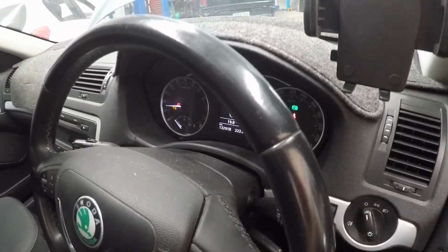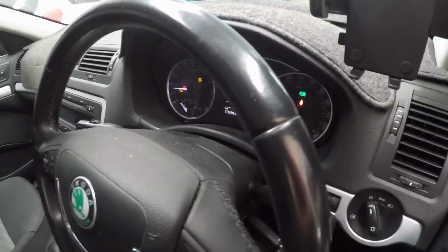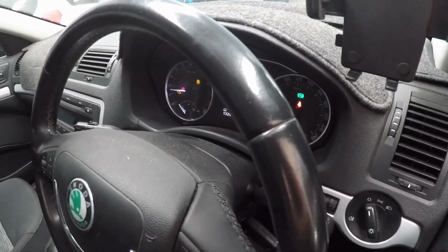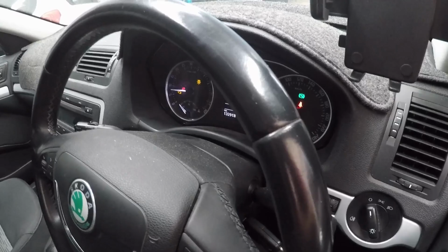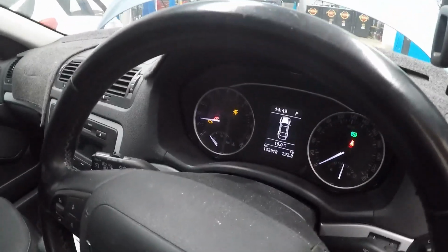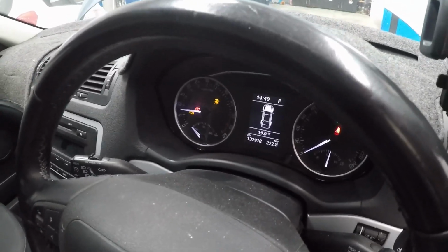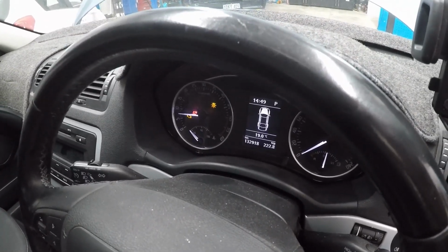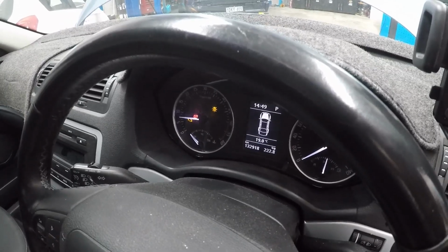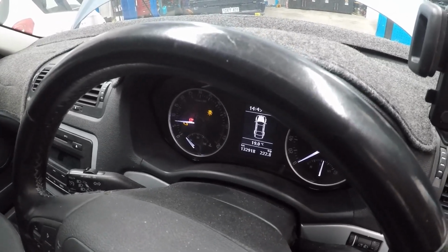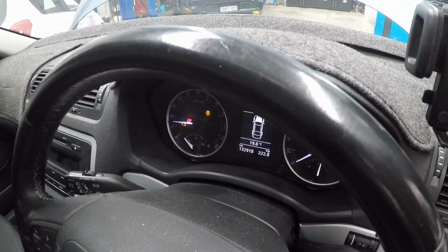Obviously that was a bit of a hard start because the fuel was depressurized, so it took a while to build back up, but we have got a perfectly running car now. As you can see, the engine light is still on because I haven't cleared the codes yet, but the glow plug light is off, which indicates there's no current fault. So I'll just make sure there's no leaks, and we'll get the scope back on it and we'll do another test, and I'll show you what the good one looks like.